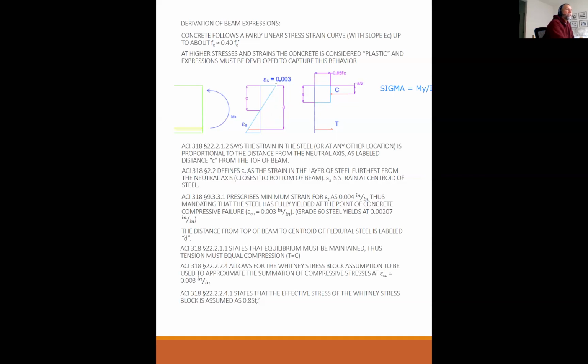So the strain is being represented by the distance from the vertical axis here. It is maximum at the top or at the bottom. And then the strain is linear from this point to this point; you draw a straight line. What that tells you is what the strain is at any given location on the beam due to this moment. That's why it's a triangle: because it's linear. Say I want to know what the strain is right there. I can use similar triangles. If I know what this strain is, and I know this strain is 0 here, and I know this distance is c, then I can get the strain at any other point.